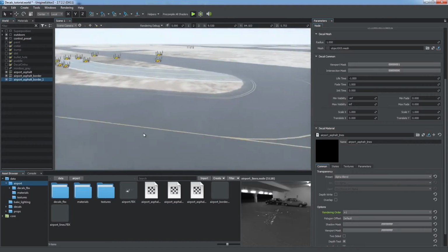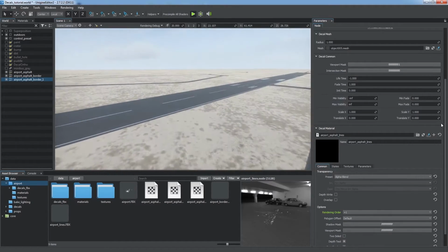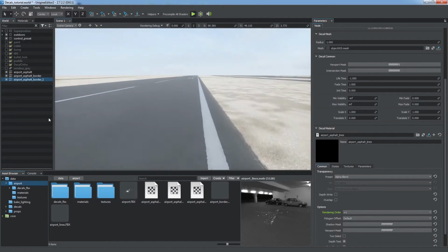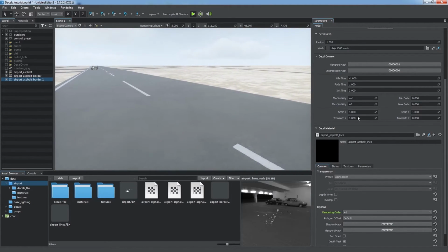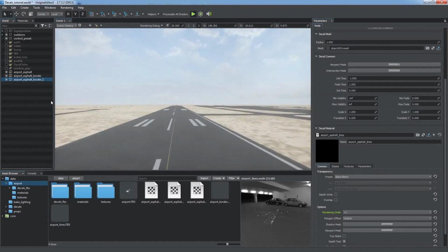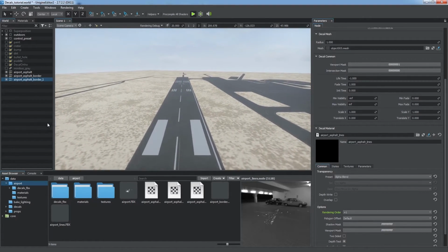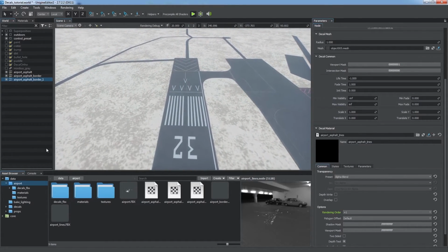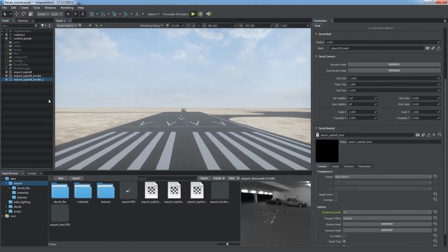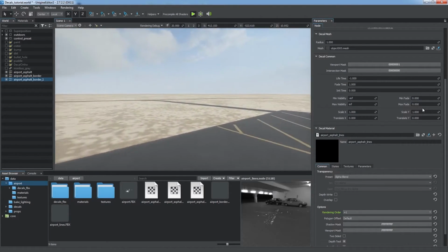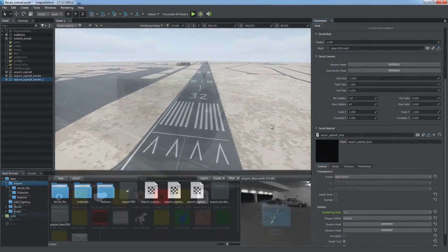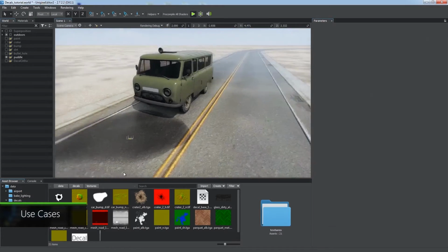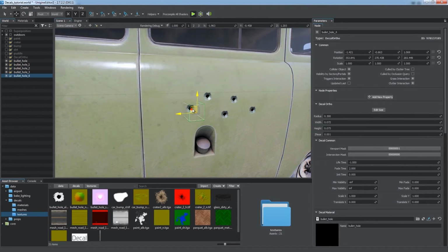Mesh decals are free from quality limitations, unlike the previous two types that depend on resolution of raster textures. A projected or an orthographic decal would require two large textures to provide acceptable quality for an area like this. Mesh decals are projected onto surface by means of orthographic projection. It provides exact matching with the surface of the landscape, which would not be possible if arbitrary static meshes were used for roads.